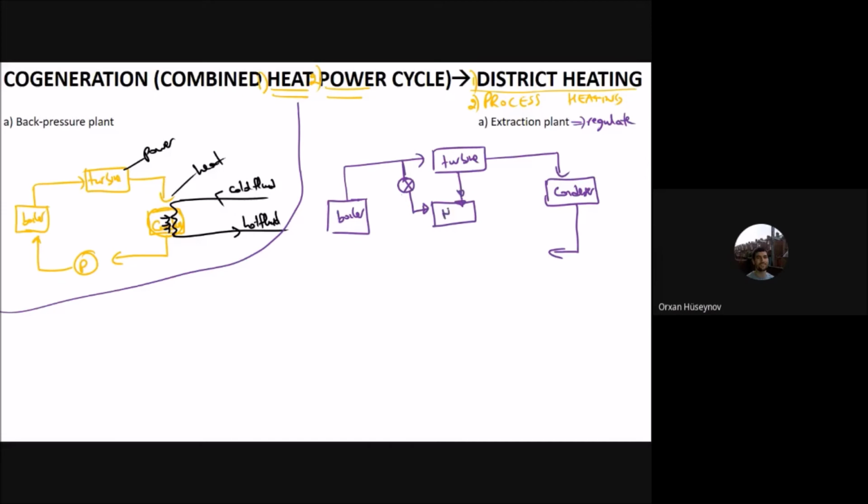So it is a heat exchanger, and this is the heat exchanger outlet, and there is the condenser outlet, and what you are doing is mixing them before entering the boiler. So here you have a mixing chamber, and you have to mix these fluids together before entering the boiler. This mixing chamber is at constant pressure, and these two have the same constant pressure, but this one has a different pressure, and this one has a different pressure. Therefore I need pumps. I will need a pump here, and I need a pump here.